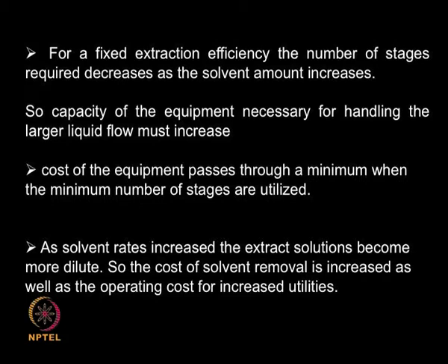So, you need to balance all these factors to decide on the number of stages. It is not only the stage efficiency. If you are fixing the efficiency, do I increase or decrease the solvent amount? Depending upon the larger or smaller amount of solvent, the stage size increases or decreases.